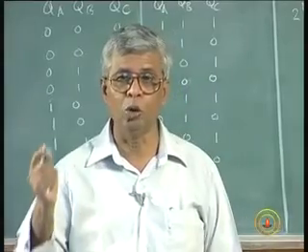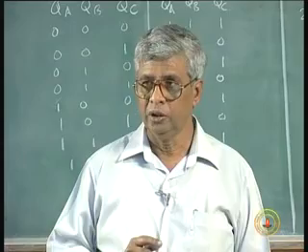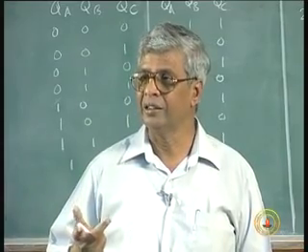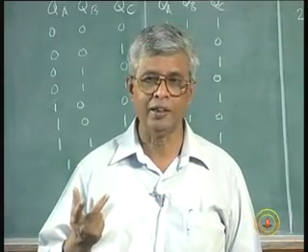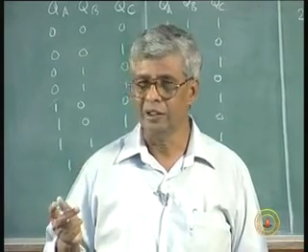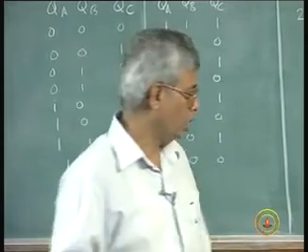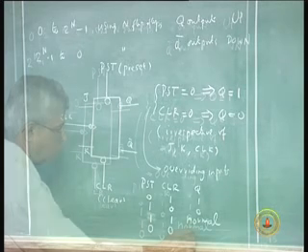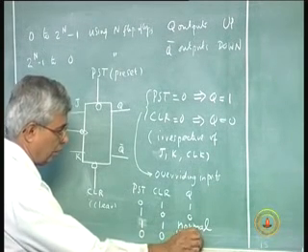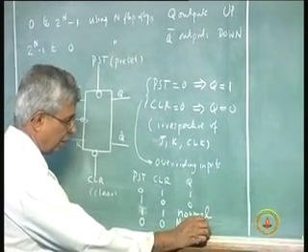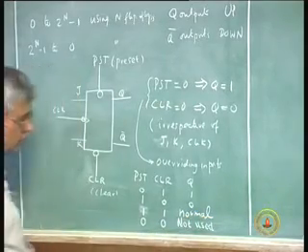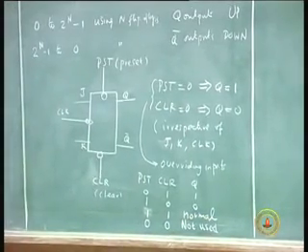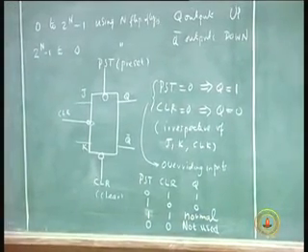Don't try to make both clear and preset 0. That means there's an uncertainty there. And I always tell you the uncertainty should be avoided at all costs in any design. So make sure that preset and clear are not made 0 at the same time.